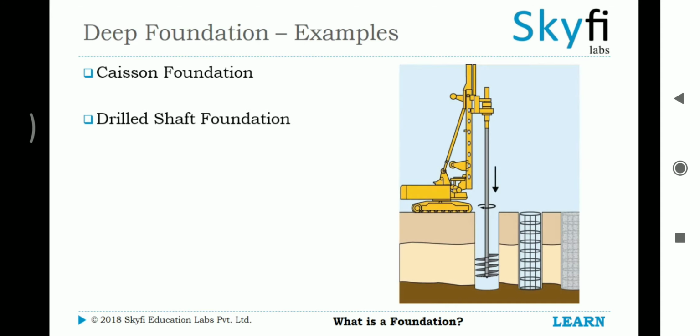In drilled shaft foundations, a hole is drilled, and then filled with rebar steel and concrete. Most drilled shafts require a steel casing, in the form of a steel plate, rolled and welded, to form a large diameter pipe. This pipe is then used to facilitate the shaft excavation.